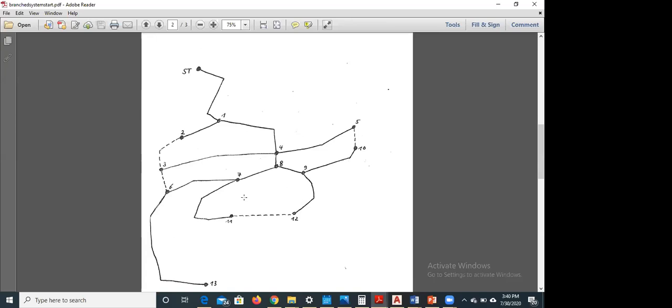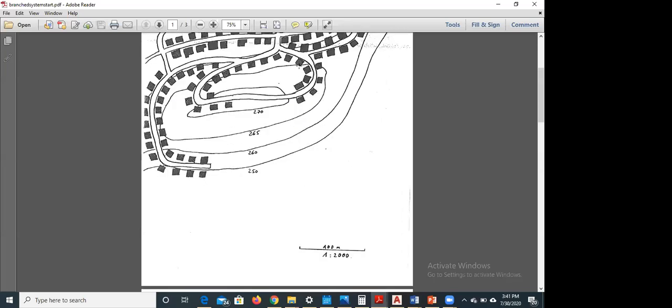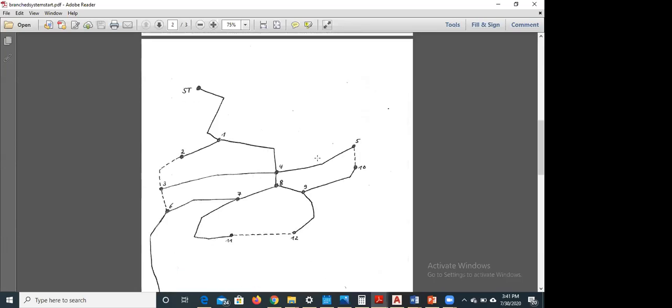And of course, basically it's wrong pipe sizing because if you use a big, adequate pipe, no matter what, there will be enough discharge in the pipe to take care of all the riparian points, all the contingent points. So in this case now, we are going to determine the discharge at point 12, and that discharge at point 12 is now for all the houses. These houses, you can see it. All these houses connected to point 12. So for now, let's assume there are 10 houses. They're not up to 10, but let's assume 10, for ease of construction, for ease of calculation.